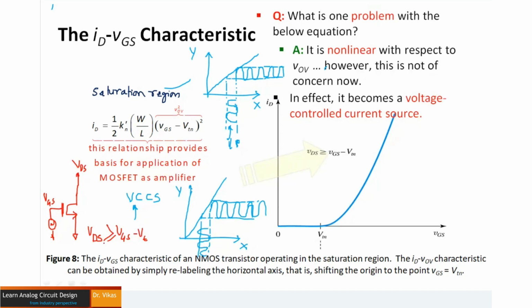Now, this scenario where you ensure that a particular MOSFET is pushed into a particular region, we call that biasing. You might have heard about biasing a particular transistor. What does that mean? Biasing a transistor means you are giving appropriate voltages such that those voltages push the MOSFET into a designated zone, depending on what kind of voltages you are giving.